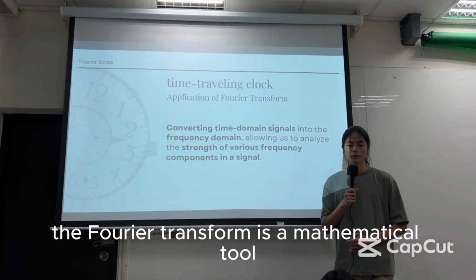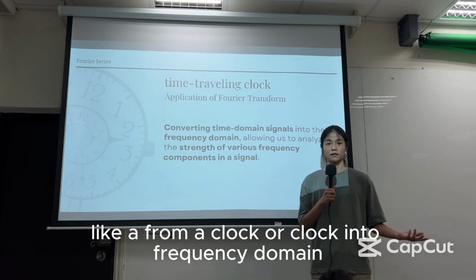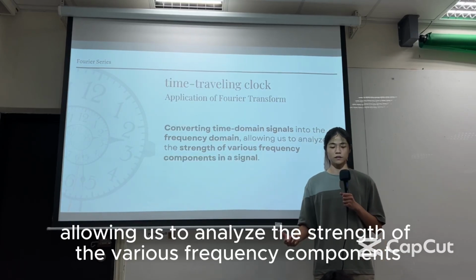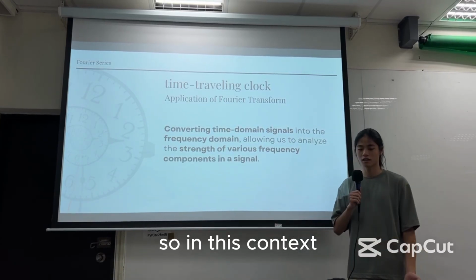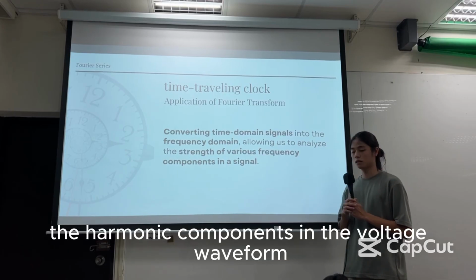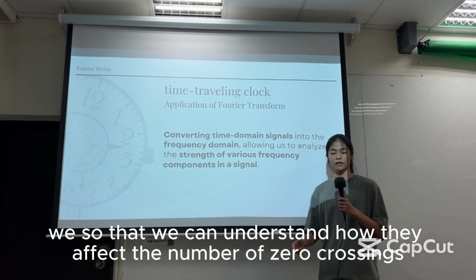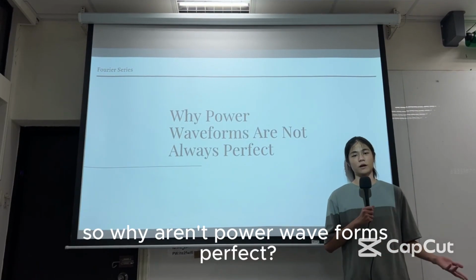The Fourier transform is a mathematical tool that converts time domain signals, like from a clock, into the frequency domain, allowing us to analyze the strength of various frequency components in a signal. So in this context, the Fourier transform can be used to examine the harmonic components in the voltage waveform, so that we can understand how they affect the number of zero crossings. So why aren't power waveforms perfect?